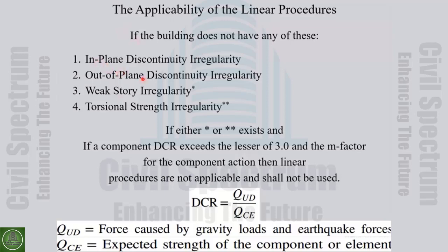First of all, before going through the articles one by one, in general, in the linear analysis, if you want to have a measure, an index of the damage, because everything is linear and superposition is valid, if we increase the load twice, every response will be multiplied by 2.